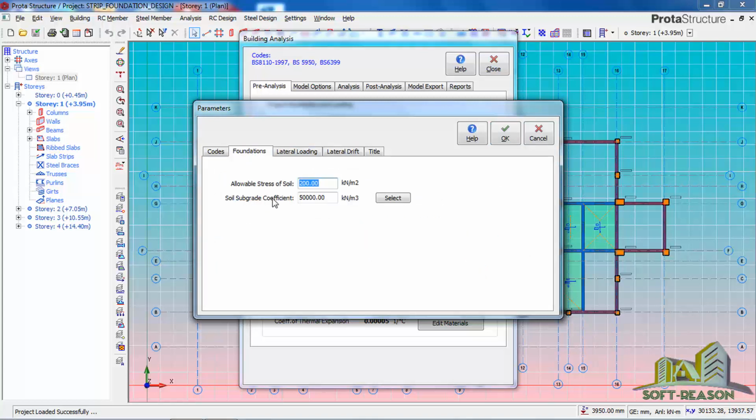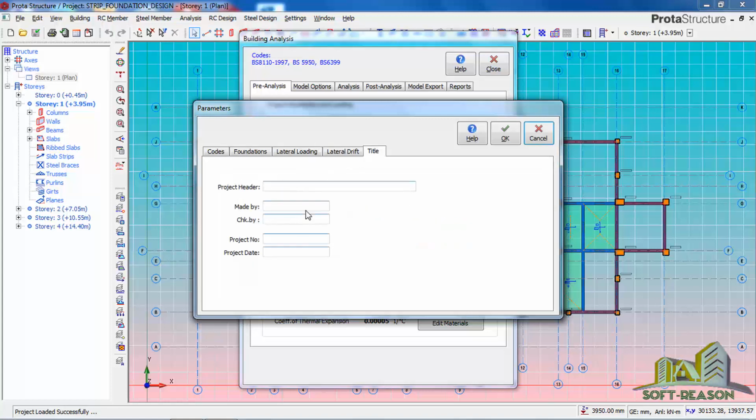In this case the foundation soil bearing capacity is 75, from 75, 60 and 80, 90. You can use strip foundations. Strip foundation is basically applicable when you are dealing with a one-story up to two-story building. From three-story up it is not advisable. After the foundation you can check some of that in detail too. This is a strip foundation.